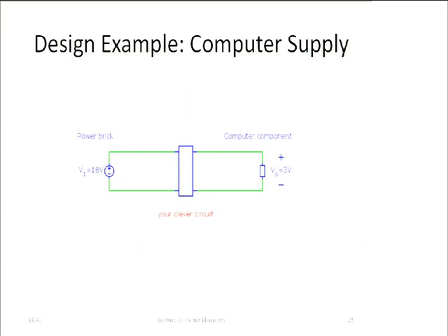Okay, so, well, interesting. Actually, not that interesting, right? But now, let's do something that is a little bit more interesting. Let's use all this stuff for something. So, if you look at the power brick for your laptop, it will be something like 20 volts or 15 volts or so. But of course, on your laptop internally, it doesn't work off 20 volts, right? The CPU uses give or take a volt or so. And so what you really need inside the computer is a way to step down from the higher voltage to the voltage that the particular component needs.